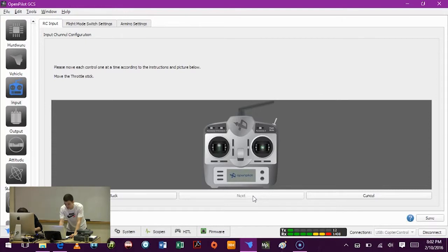And then we need the flight controller and transmitter now. Plugging our cables in real quick. What you're going to do here is just tell the flight controller the high points and low points that the transmitter gives, so it knows when you arm it not to spin up the motors to a very high position. It also knows that when you're going left, you want to go left, you don't want to go in the middle or right. So it gives you just the center points, essentially. Ready?